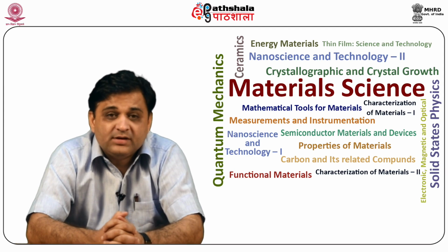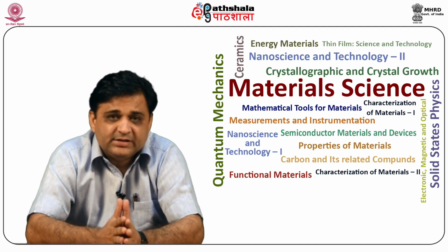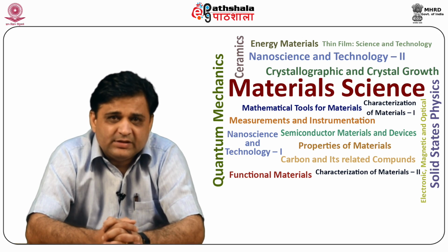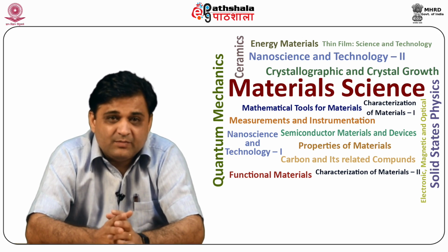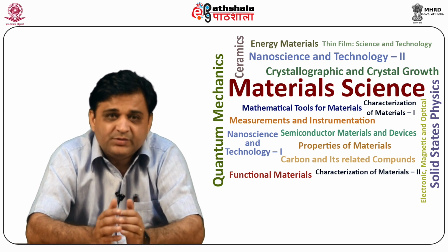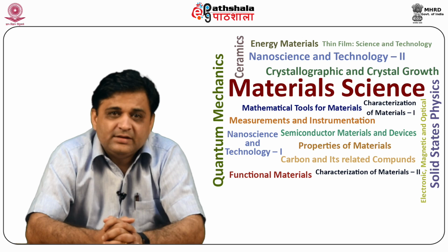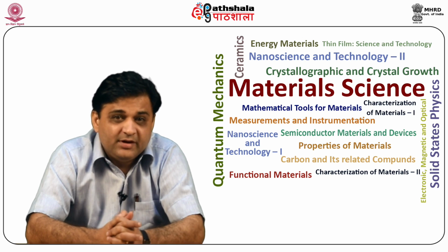Requirement for the CVD process. Now when we are depositing a film through CVD, chemical vapor deposition processes, what are the requirements? The precursors have to be volatile gases. An example is SiH4, called silane, a popular precursor to deposit silicon. It should be in a gaseous form, and the chemical reactions need to be thermodynamically predicted to result